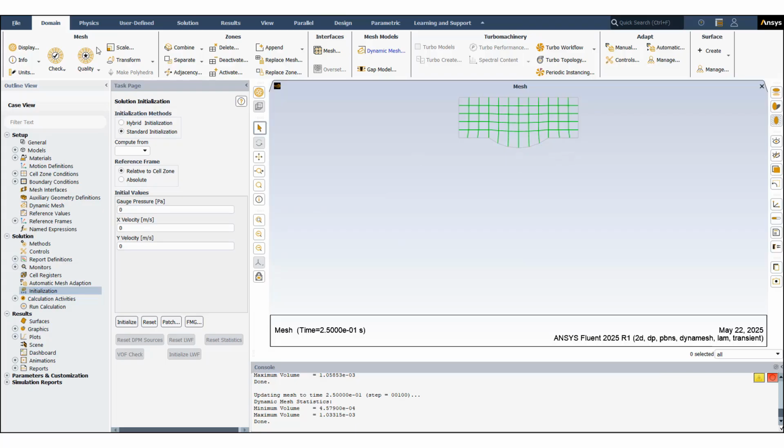So we have to exit Fluent, relaunch Fluent, read the mesh again in the initial form, and initialize the model. After being sure that everything is correctly set up for dynamic mesh motion, read the mesh in its initial form, initial shape, and then start the simulation.